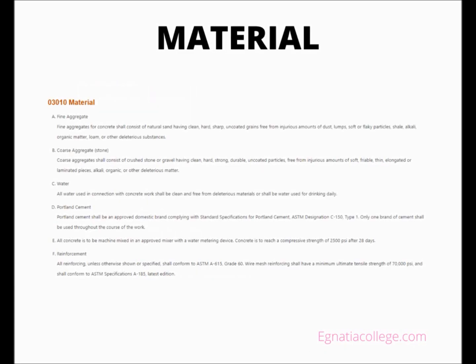Delivery and storage. All materials shall be delivered, stored, and handled so as to prevent the inclusion of foreign materials and the damage of the materials by water or breakage. Packaged materials shall be delivered and stored in the original packages until they are ready for use. Materials showing evidence of water or other damage shall be rejected. Brick shall be chosen by the owner from approved samples. Concrete block shall be load-bearing, hollow concrete masonry units and shall conform to the standard specifications of ASTM C145-71.